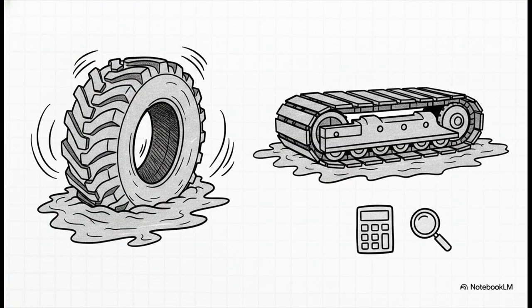For Building ABC, John reviews the site plans and realizes the ground conditions are poor. We're talking muddy, soft, unstable terrain. Because physical site features always dictate the method of construction, John knows standard wheeled machinery would just sink right into the mud. He must specifically select track-mounted bulldozers. This single-site observation immediately alters his entire pricing structure.